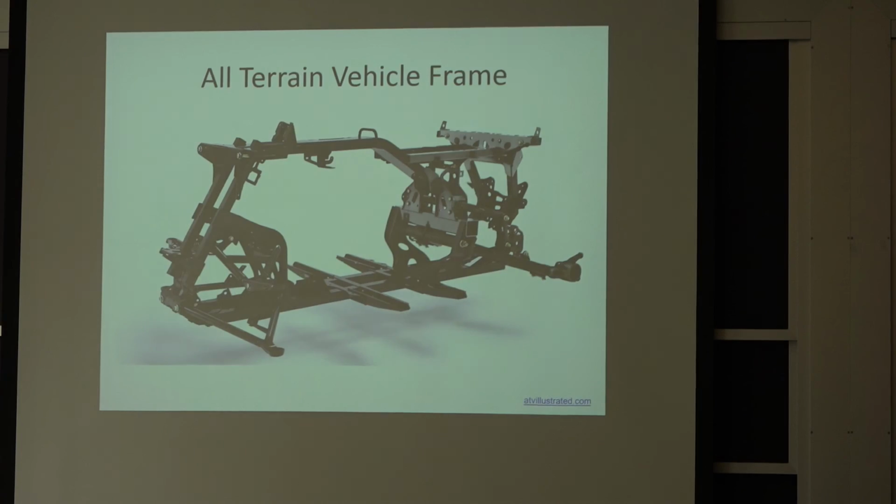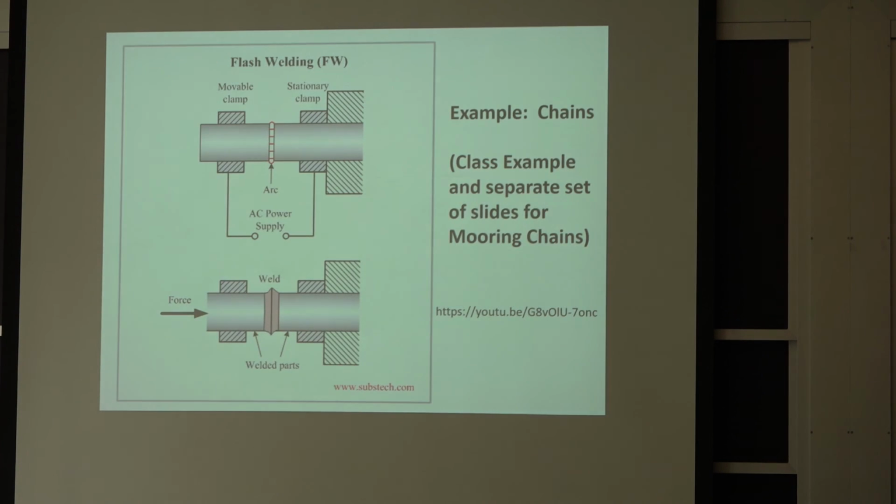If making steel was that easy, maybe I wouldn't have a job. We talked about this a little bit last time about other ways you'll weld that don't involve the electrode type process. So we have friction welding, flash welding, where you put the arc on the two pieces and you ram them together. And resistance welding is just a small variation. Again, you clamp the two pieces together and you induce a current between them and you have a local spot fusion. They're used a lot.